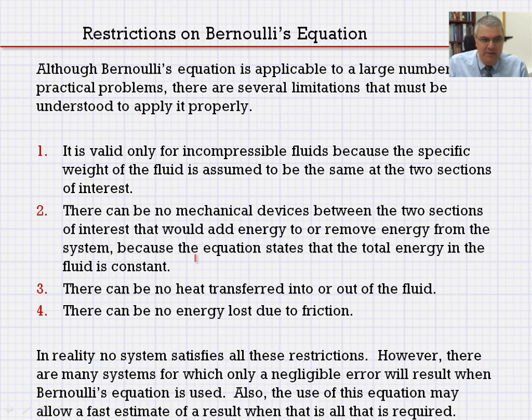There can be no mechanical devices between the 2 sections. That is pumps, any kind of suction device, any other device that would either add energy or remove energy from the system. Again, when we say adding or removing, we're talking about conversion of energy from one form to another. There can be no heat transferred into or out of the fluid.